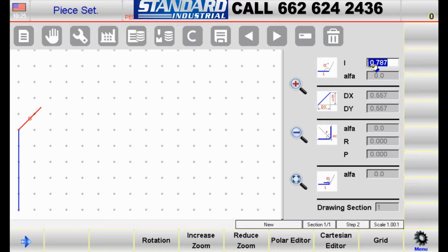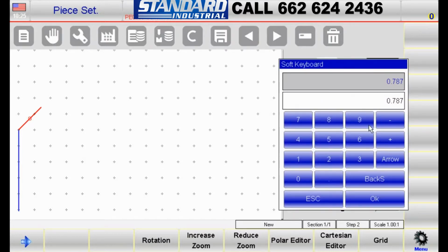If we needed to move back and correct an error, we could simply click on the back button and you'll see that the information we previously entered scrolls back into view, and the tangent that is now active turns red. So we could make an alteration at that point, but instead we're going to go back to our current line. It is now active because it has been highlighted red, and once again we're being prompted for the length of this line. This time we're going to say the line will be 3 inches long.